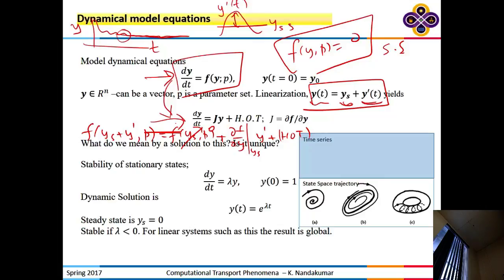The concepts that we are seeing are all applicable to the Navier-Stokes equation. It's a simple ODE, and we will make the connection from Navier-Stokes equation to ODE by simply discretizing all the spatial variables. You get maybe a million ordinary differential equations, but those equations will have a Jacobian, which will be a million times a million. That depends on how many grid sizes you have.